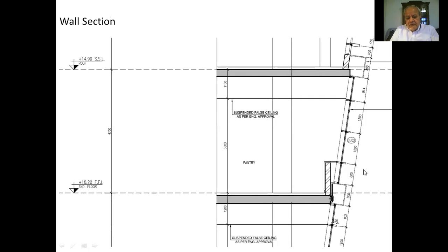It can be 1:50, 1:20, so that you show the details of the connections of the concrete and brick and aluminum and glass and marble and cladding. So this is an important element that is related to the design of the building facade. This is how they reflect each other and integrate with each other.